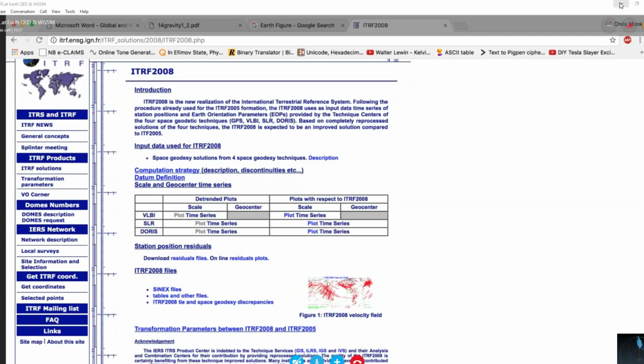to establish your local datum to your local coordinate system of the town, city, or wherever you're at. And you just set them up and you let them go for a week until they calibrate themselves. These days, they use this constant velocity, and you establish where you are as far as in motion as a point in space and time. And then from there, you just drive a stake in the ground, essentially, measure that to a pin, call that your starting point, and then from there on out, it's all flat. Right? It's all level transits from point to point to point.